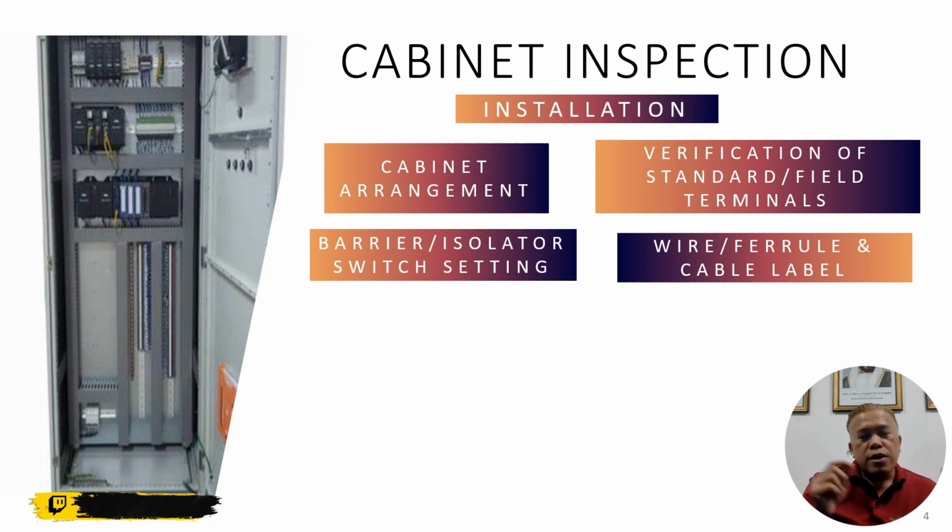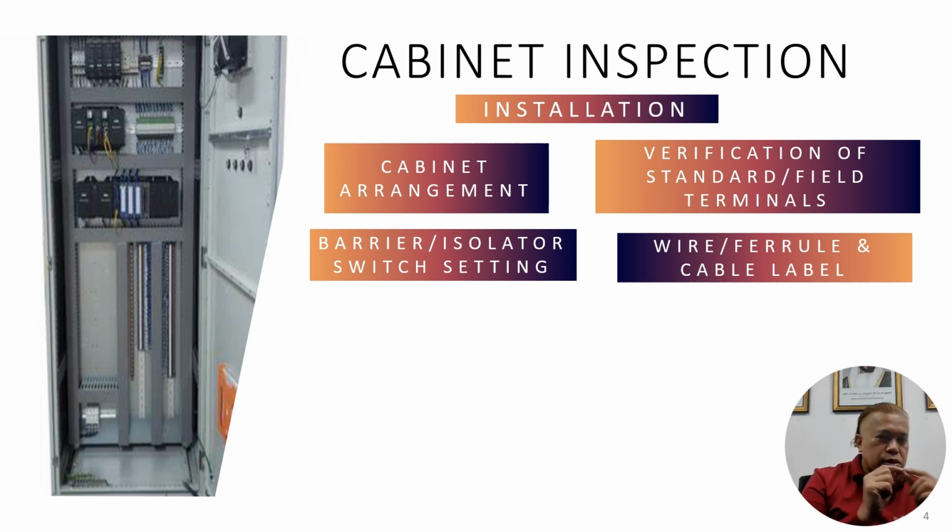Is it based on the interconnection drawing? You need to check that it is correct and can connect to the other end. That's why the most important things during commissioning and testing are our panel and cable tag.